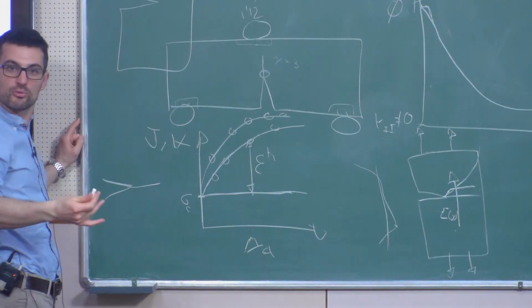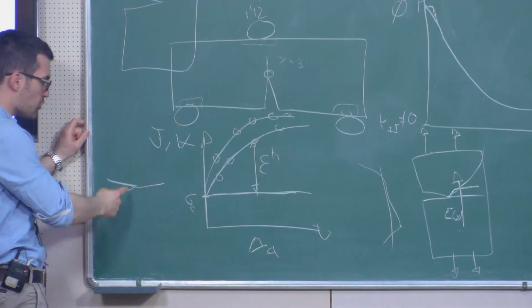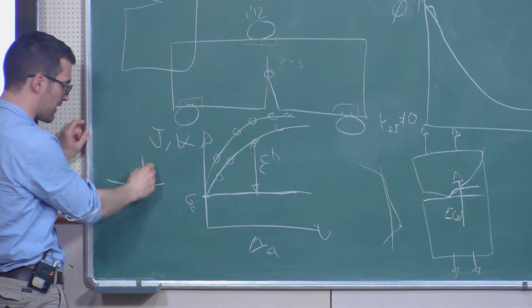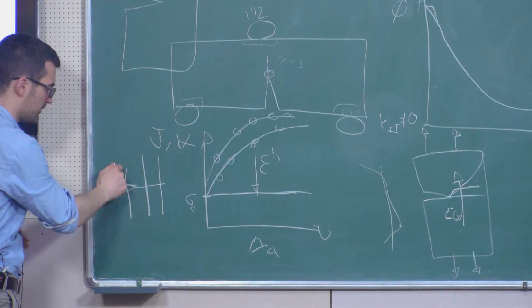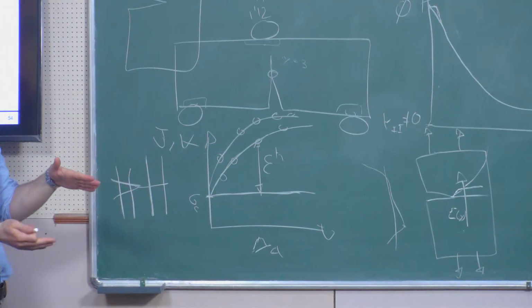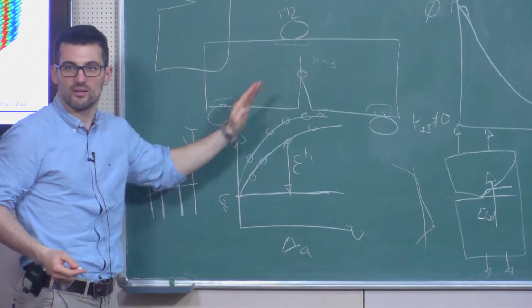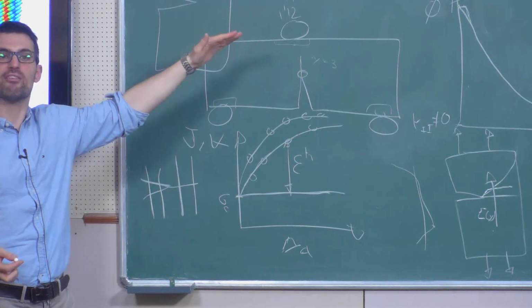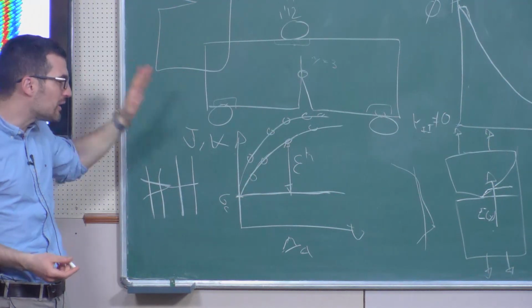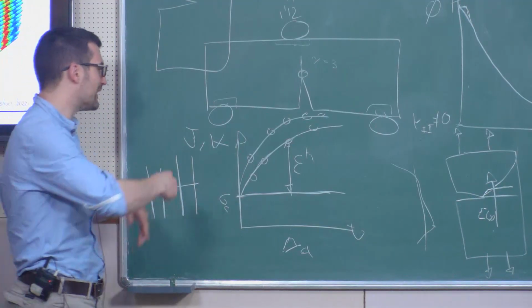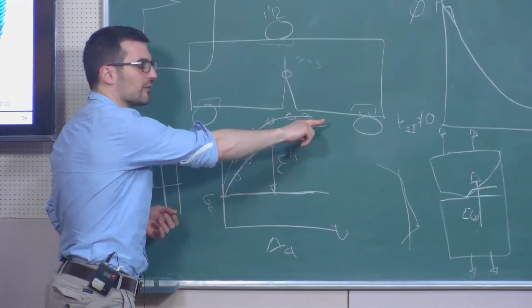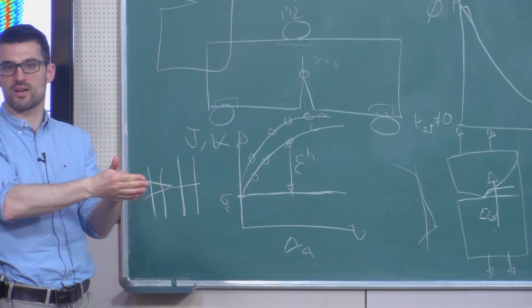In composites, good for us, they have good fracture toughness. You have a fiber bridging effect, so you have these fibers that are bridging the crack, they're closing your crack, basically. Because those fibers are closing your crack, you get a toughening effect, which is good. We get an enhanced fracture resistance. But all the models that I've seen so far, what they did is first they ran an experiment, and then they had some sort of fitting of that toughening effect, and they embedded that fitting effect into the model.